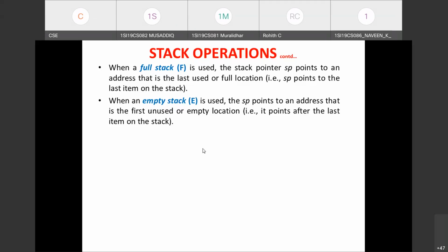If you have considered ascending stack, then after inserting the data, we'll perform an increment operation on the stack pointer. If you have used descending stack with an empty stack, in that case first we'll insert the data, then we'll decrement the stack pointer by the value, say 4. Since each data is 32-bit here, it will be decremented by 4. This is about empty stack.